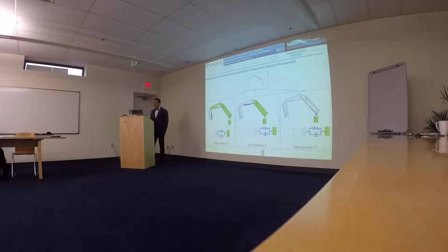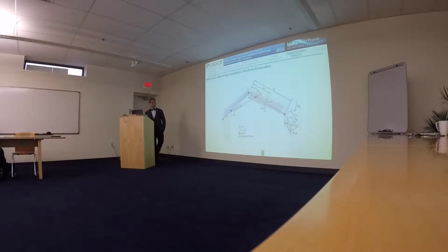So in order to understand how the oscillation of the payload is reflected in the pressure, which is what we are measuring, I made a kinematic study of the machine. So taking as a reference the machine in this position, we can simplify the kinematics in this way. And if we assume the load motion is sinusoidal, as for example a single pendulum, we can write the acceleration in the x and y axis of the payload.